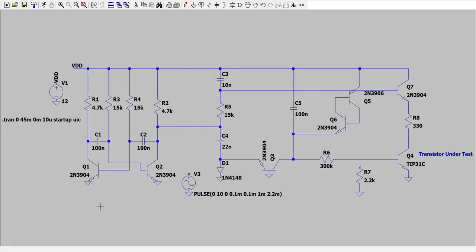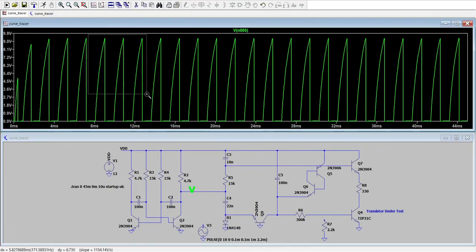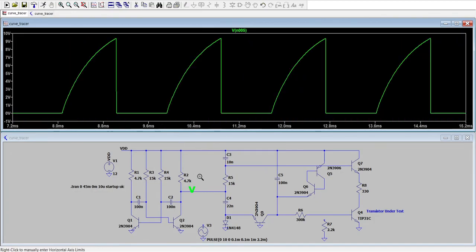We'll analyze each part separately starting from this circuit here. You might already know it, this is simply a bipolar astable multivibrator, and it gives out a sort of square wave. Why sort of? Well, if you look at the voltage here, you can see that whoever designed this circuit chose R1 and R2 values so that the rising edge is very slow. But I'm quite sure this is intended, and you'll understand why in a moment.